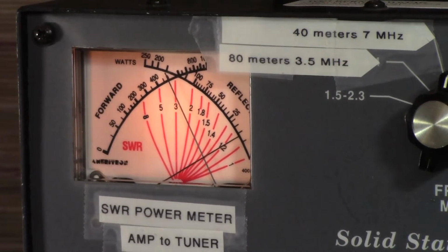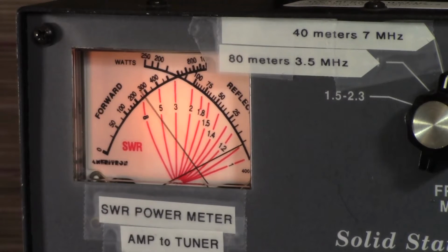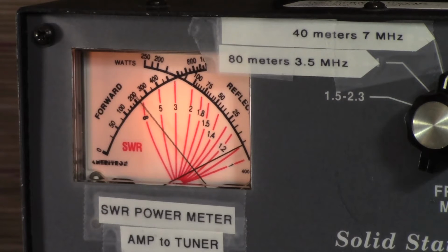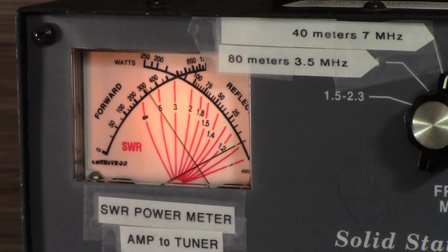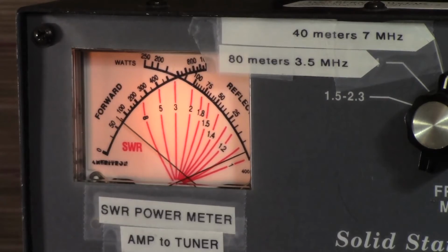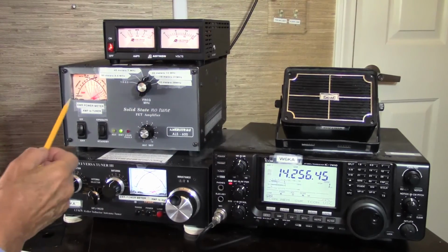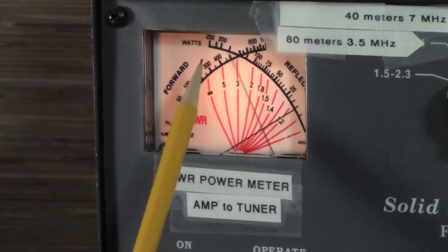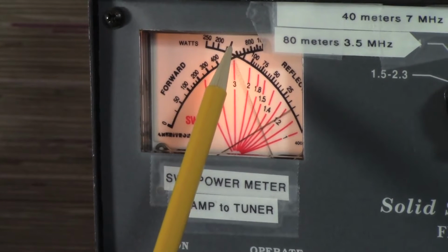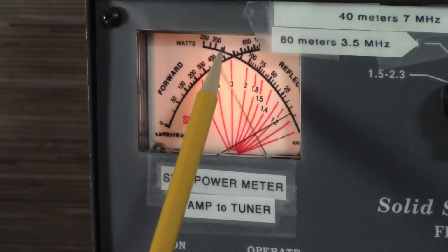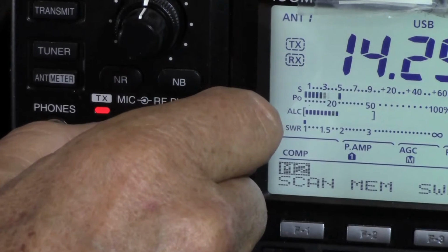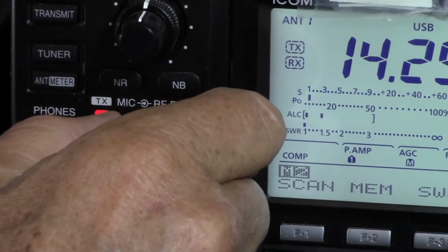Speaking about 6 inches or 4 inches away from the microphone, we're bouncing about to 600 watts PEP. Keep an eye on the power output on this meter. It should not go much above 600, and if it does, you should probably back down on the RF power gain a little bit. It's hard on the amplifier if it's being driven to more than 600 on peaks.